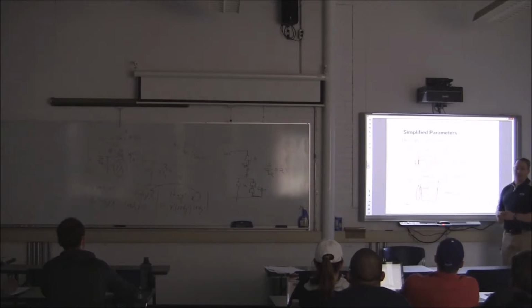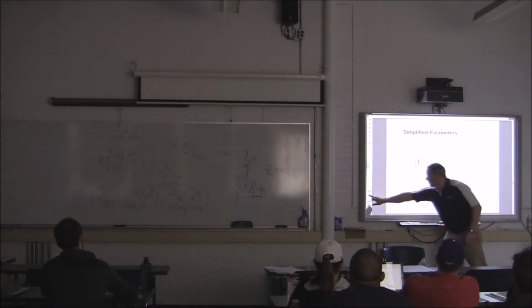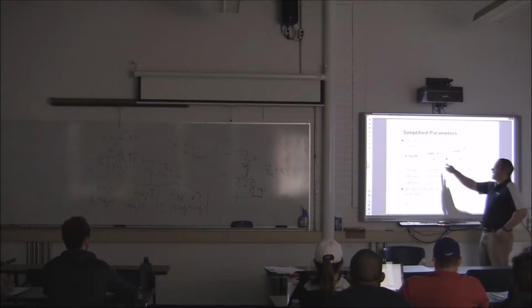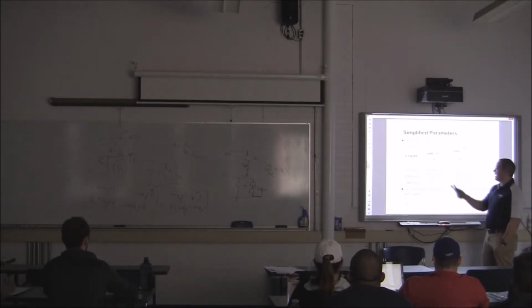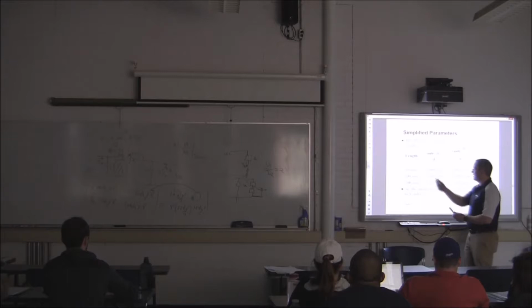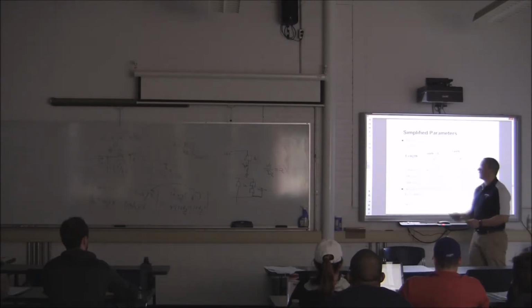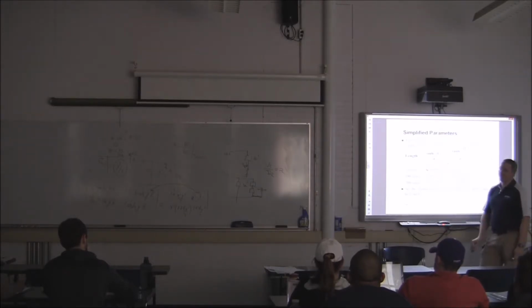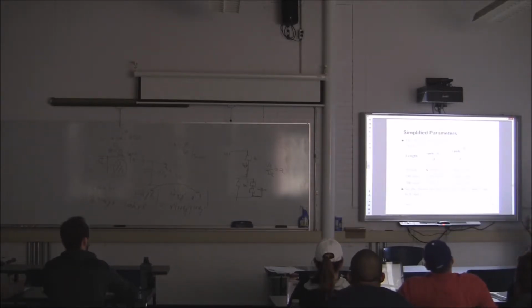So these are written based on the original ones plus a scale factor. And the unit length determines how hardcore we need to be. If we take a typical unit length of 50 miles, and take hyperbolic sine of gamma L divided by gamma L, what is this number right here? That to me looks close enough to 1 at an angle of 0, doesn't it? So how much scaling needs to be done for a line that is 50 miles or less in length?